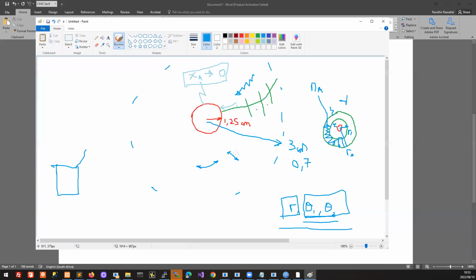If we are traveling along in a tube like this, and we consider two positions here and here, just the fact that the concentration is constant means that the molar flux there equals the molar flux there. That was fine, but that was also in a special case where the areas were identical. Remember, the cross-sectional area here is equal to the cross-sectional area there. So we don't have that situation anymore. Now we have two different radial positions. Let's make this bigger.